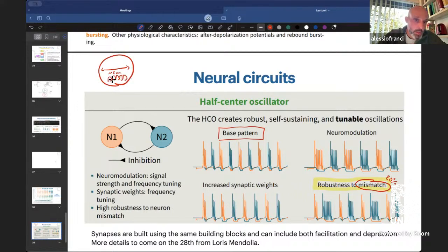And so a transistor here will be very different from a transistor here, because the way in which they put the product that dopes this wafer diffuses in different ways. It's not a perfect process. So essentially, doping here will be different from doping here, and this is what's called the systematic mismatch. So you have transistor mismatch, which is even for close-by transistors, and then systematic mismatch, which is due to the fact that they're in different parts of the wafer.